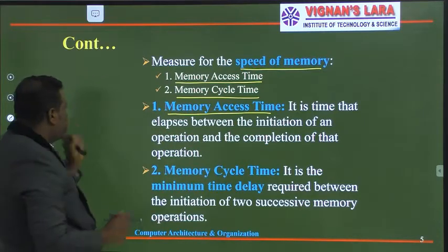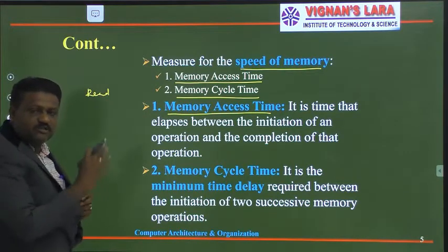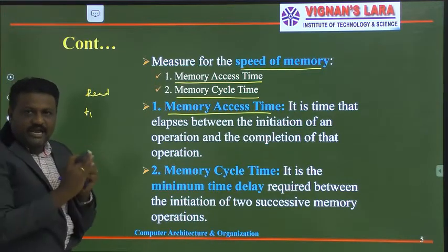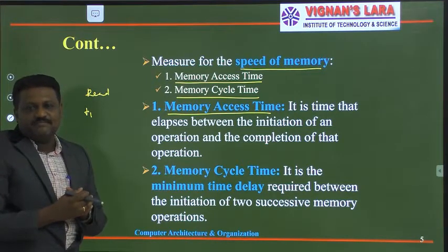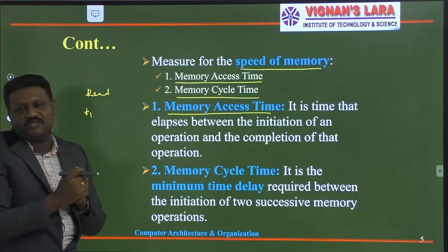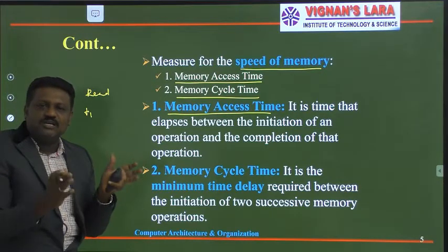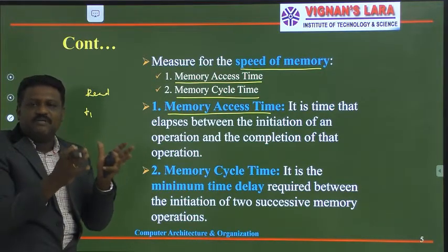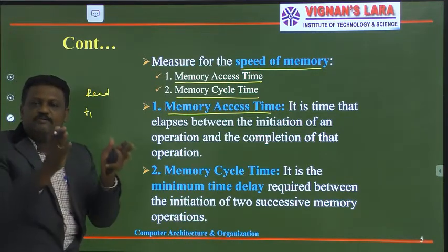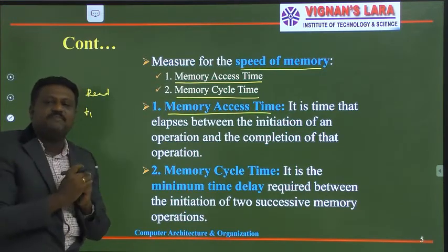For example, my processor is going to do a read operation on the memory. At time instant T1, our processor generates the address of a memory location. Later it will issue a control signal, and based on the control signal, the memory can communicate with the processor. Here our operation is read, so your memory places the selected location information on the data bus.